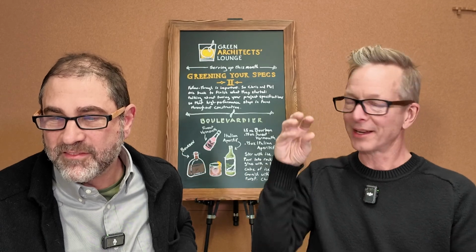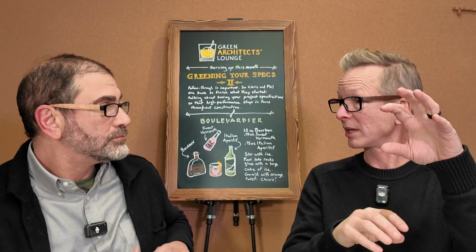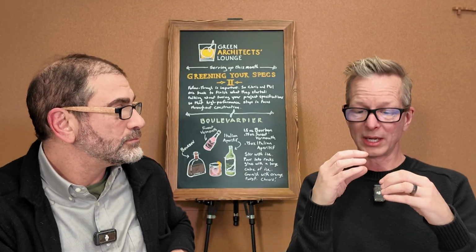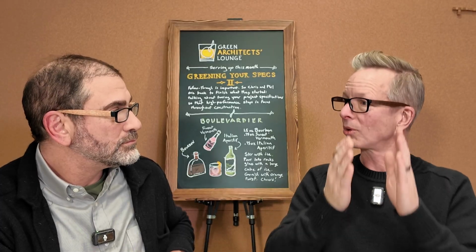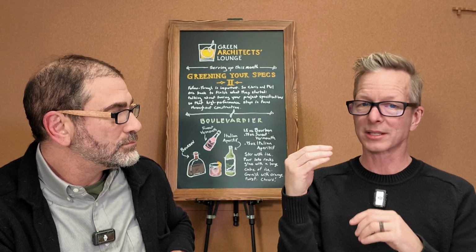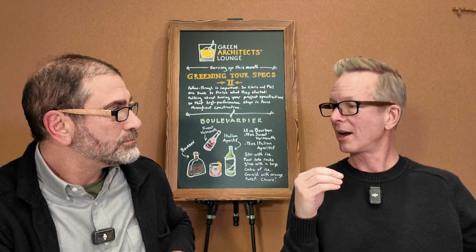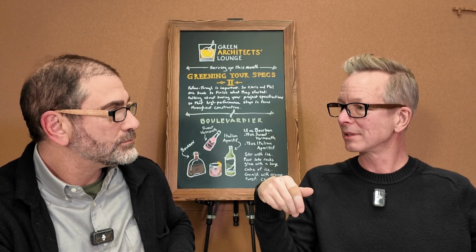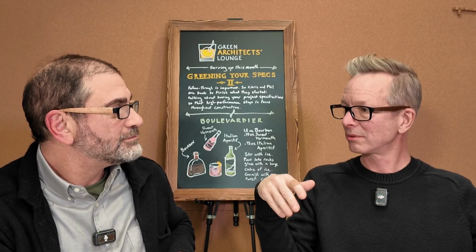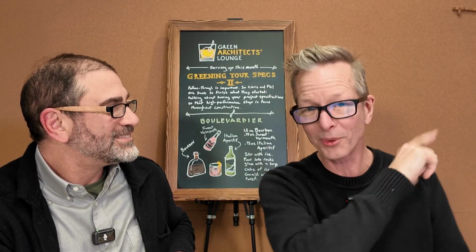Basically backdraft damper. You shove it into the ductwork like in your bathroom exhaust fan. You shove it in right where your thermal envelope is. You want it right there, and that's where it's going to stop that cold air from getting back into your fan and dropping down on you. Even though all this equipment has backdraft dampers, they're just little flaps. And so, of course, on a windy day, you can be under your bath fan wondering, where's that draft coming from? Not with one of these, baby. That's so cool. And they're so cheap and dumb and easy.